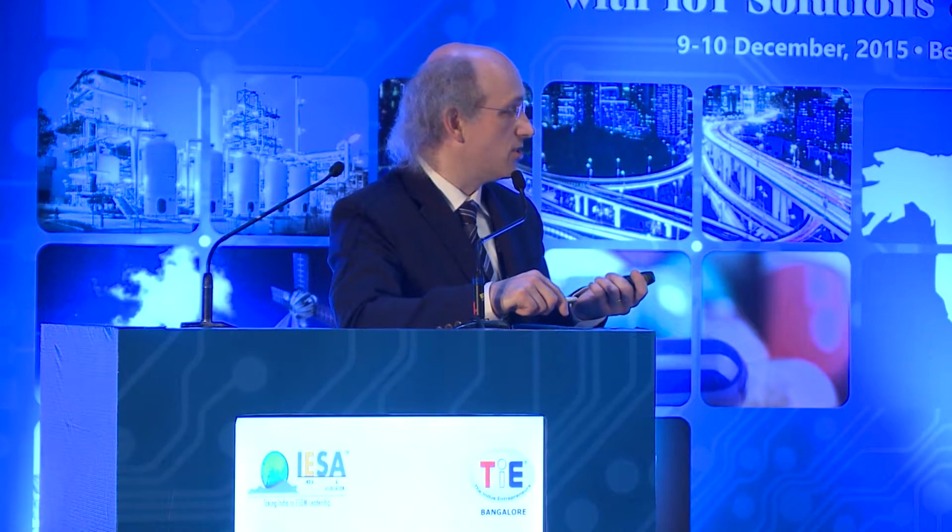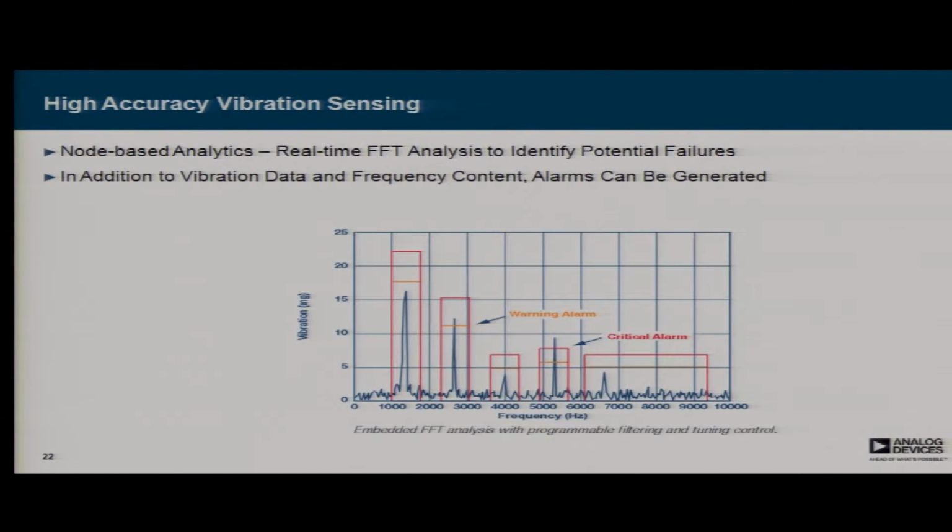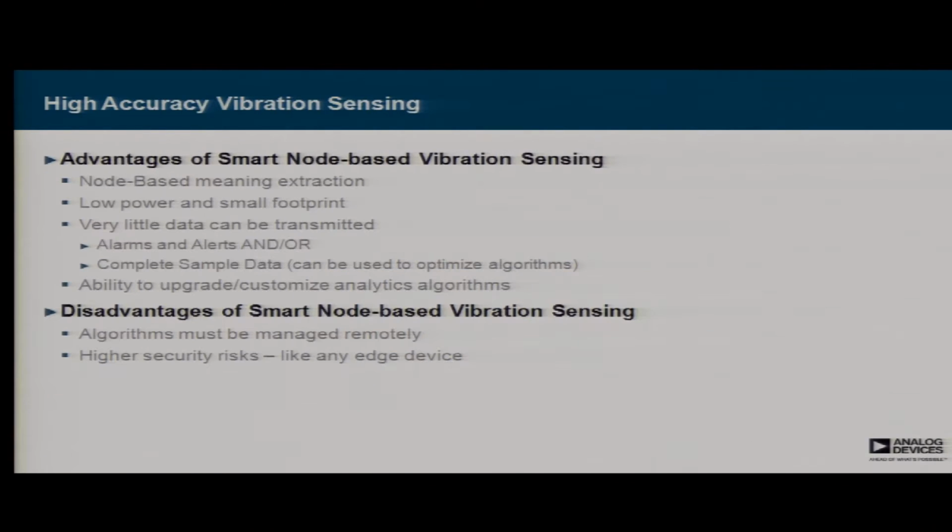An example like this is an FFT, right? Typically in a vibrating system like a motor, harmonics will pop up in relation to different potential failure modes, like a bearing that's about to go wrong, or something that's potentially wrong with the load. By monitoring for various harmonics, we can actually see if something is going to fail. So it's a very early leading indicator before there's any evidence anywhere else in the system. We can see that, yes, something is about to fail, okay?